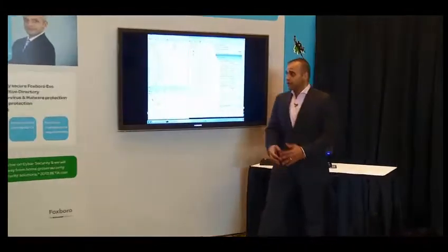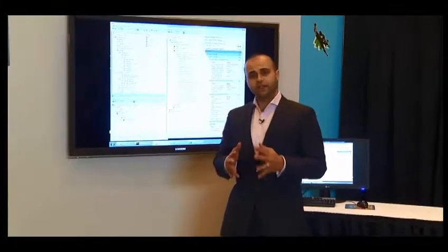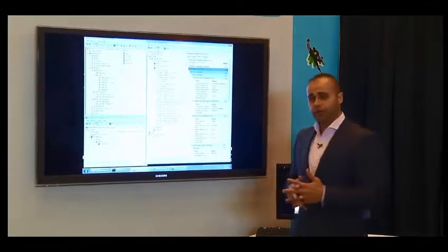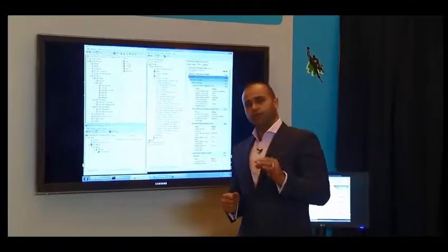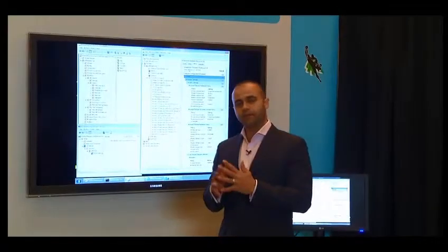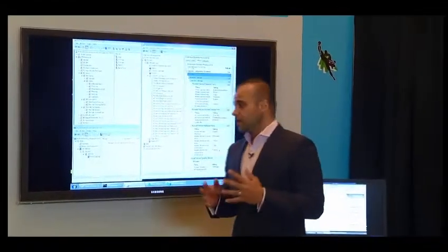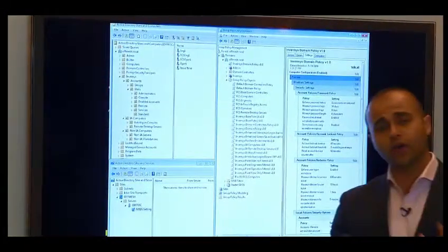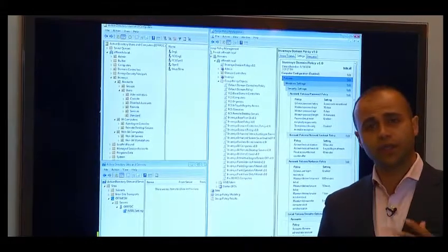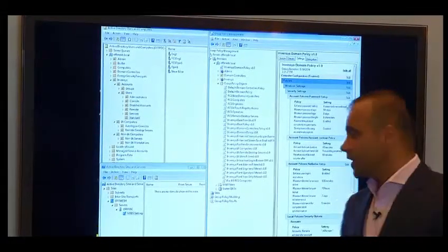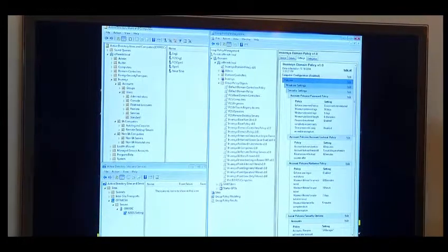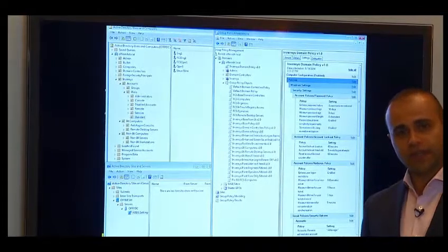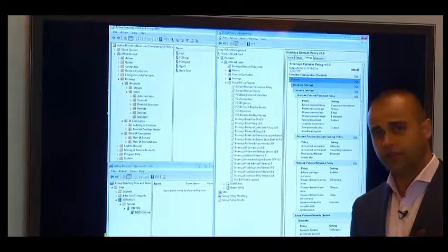Absolutely, Gary. With regards to the standards, we're seeing specifically in Europe and the Middle East that ISA 99 or IEC 62443 are becoming very, very popular. They're becoming so critical that we have to maintain that same compliance even through the proposals process. So what we've done with some of our clients in the past is implement the ISA 99 over the ISO 27001 Information Security Management System framework. What I'd like to show you is one of those primary components in a little bit more detail, and that's going back to the AAA protocol that we talked about a couple of seconds ago. And again, that's authentication, authorization, and accounting.